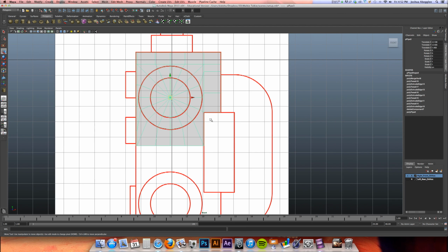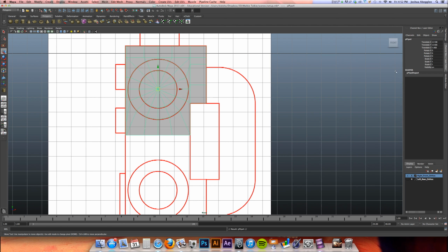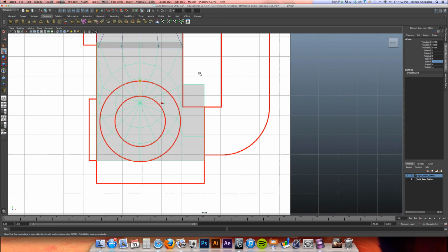All right, now let's go ahead and take this object and I'm going to duplicate it. That is done with Command or Control D. And now I'm going to scale this -1 on the y-axis. Whoops, not -11, just -1. You can see what that's done is that's created, for the most part, a mirror image of the piece of geometry that we just created.